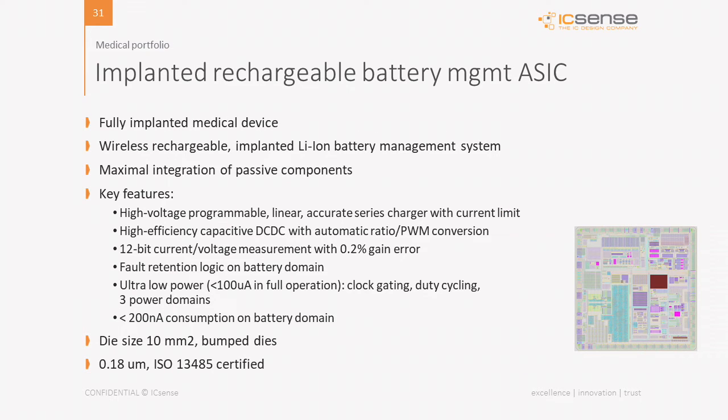This one is another example of an implantable rechargeable battery management ASIC. In this case, it was a fully implantable medical device, which is being used for wireless recharging in combination with a lithium-ion battery management system. Also here, lots of interesting DC-DC, current and voltage measurements and detection diagnostics have been implemented on chip.